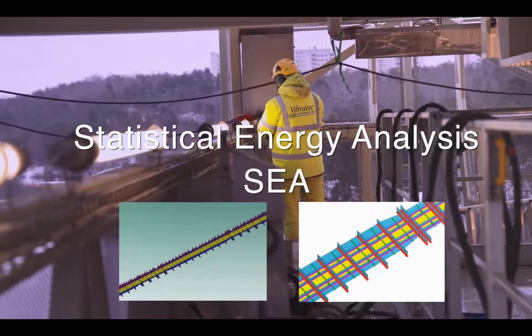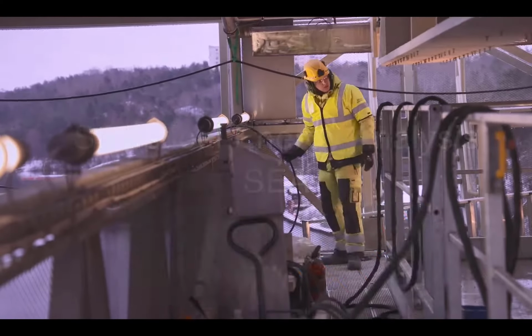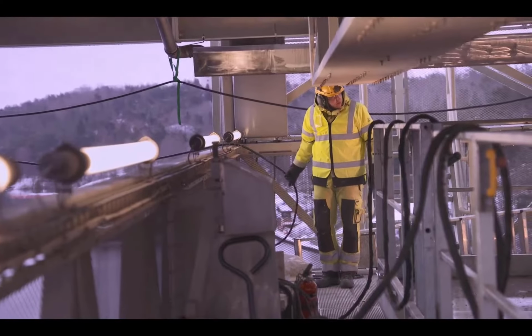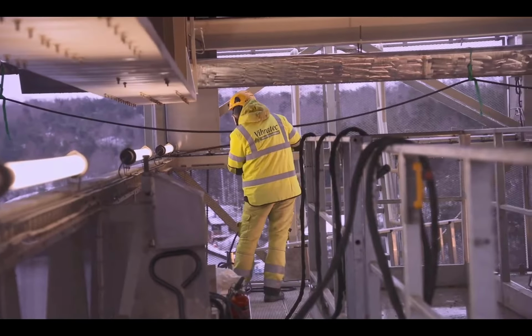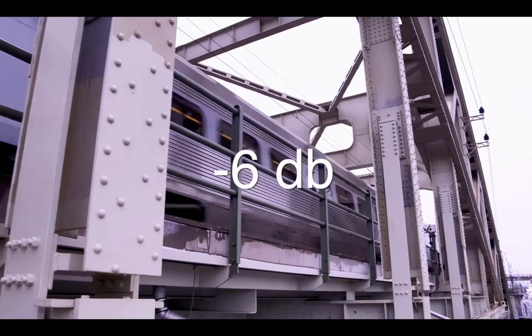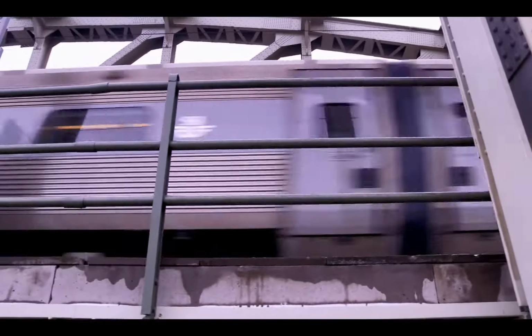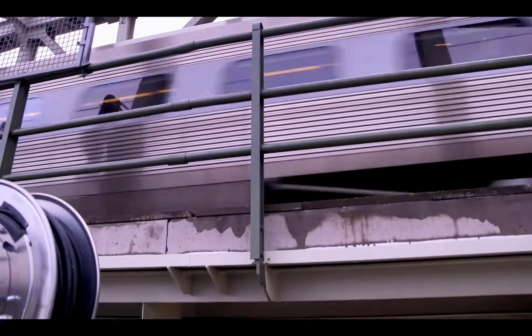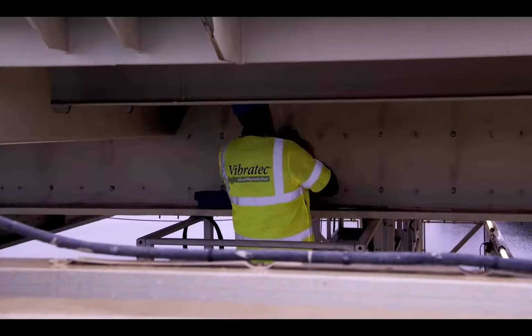By use of statistical energy analysis, SEA, the future noise reductions could be calculated for different materials. Vibratech could conclude that damping the bridge structure would result in a 6 decibel noise reduction using the CLD method. On the basis of this analysis, the transport agency decided to implement measures for the noise damping of Årsta Bridge using constrained layer damping panels.